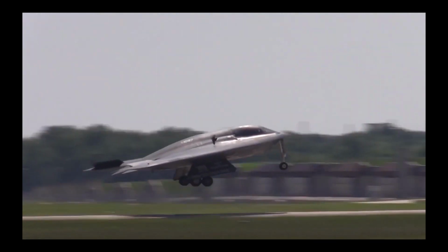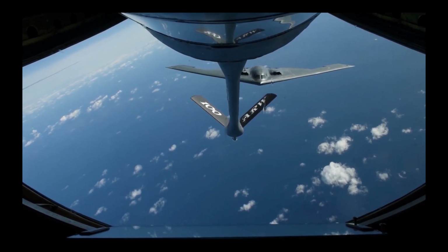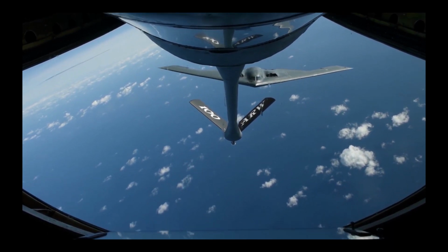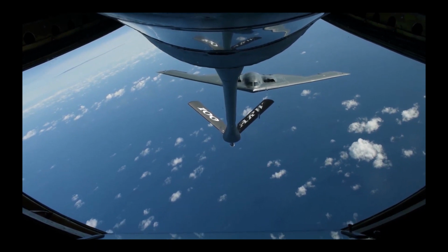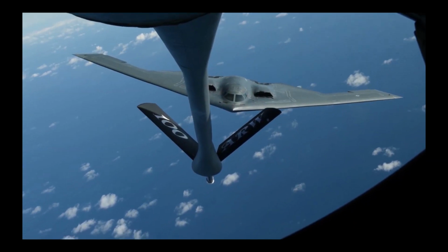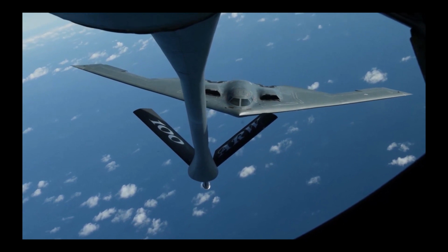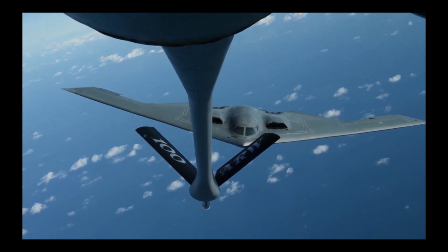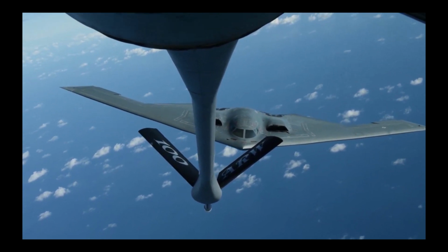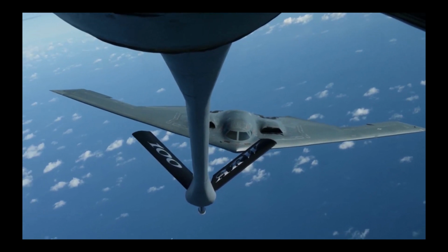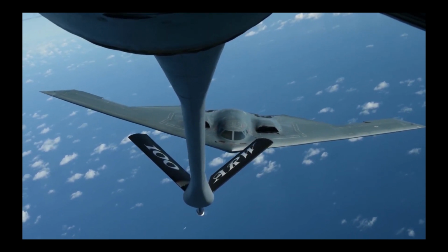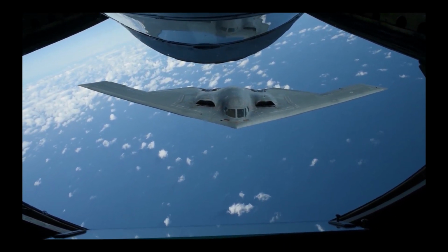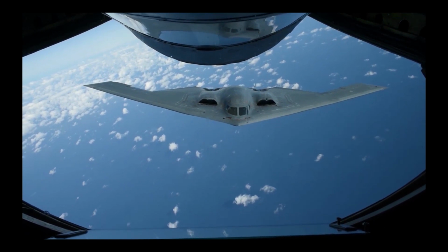Because the whole aircraft is essentially a wing, you're talking about bending the whole aircraft during maneuvers at high speed and low altitude, and also the controls to alleviate load while still trying to maneuver the airplane. 80% of the wing bending moment came from the first bending mode, which had a node line behind the outboard controls. This was a significant problem because it would really change the structural dynamics of the aircraft and make it completely unstable.